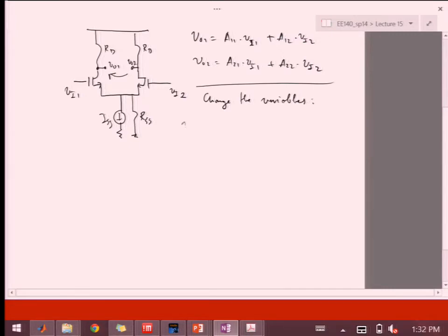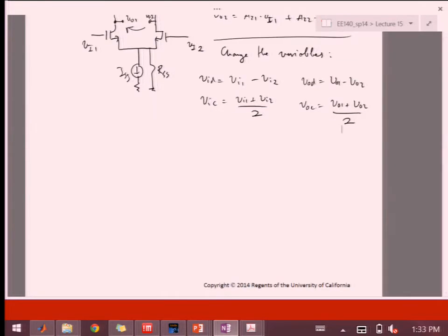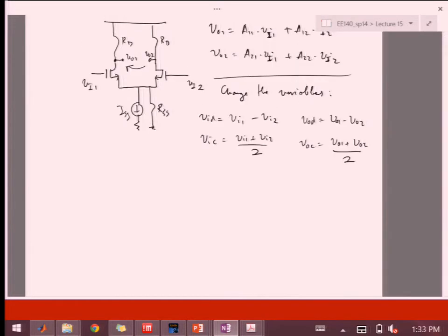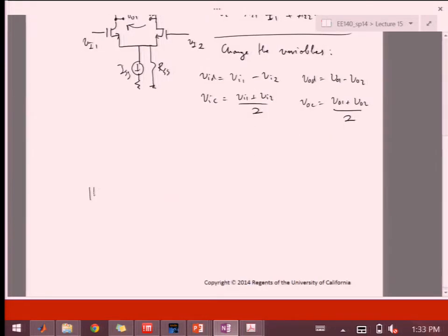Okay. So we're going to say that VID is, sorry, we'll do this lowercase, VI1 minus VI2. Say that VIC is VI1 plus VI2 over 2. VOD is VO1 minus VO2. And VOC is VO1 plus VO2 over 2. Okay. So if you do this, then you can kind of represent this same thing by doing a different drive.